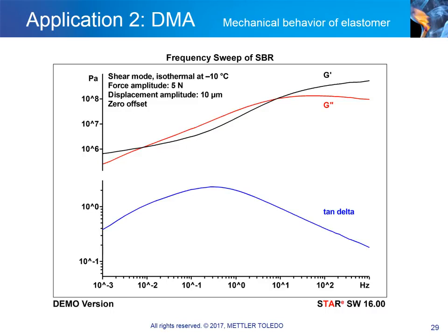At low frequency, the material is soft and behaves in a rubbery manner. As frequency increases, the material stiffens and becomes glassy. This demonstrates the ability of this material to behave like a rubber at frequencies in the millihertz range, and conversely, to behave in a glassy fashion at frequencies in the kilohertz range, while being held at the same temperature.